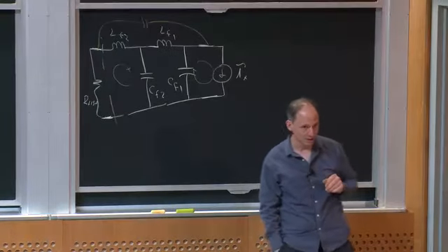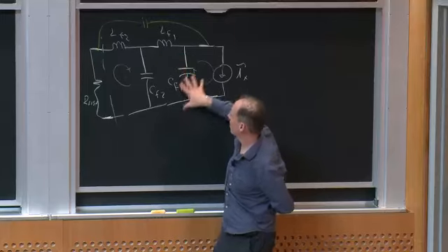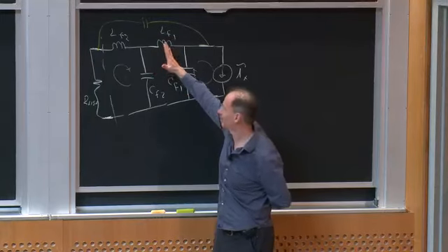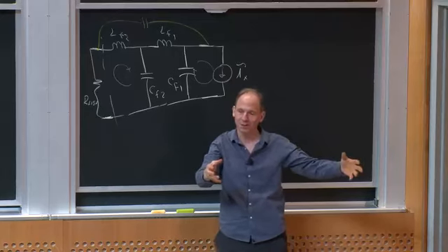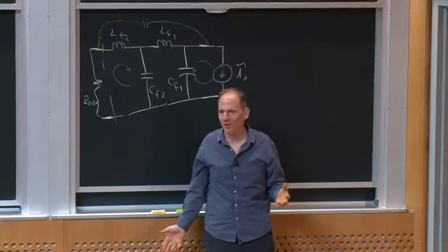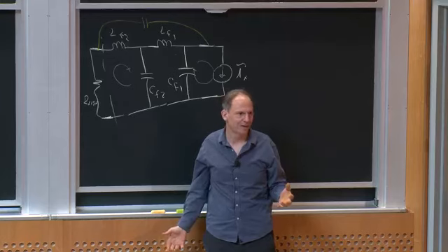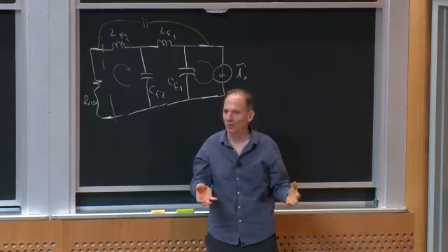What they do in commercial EMI filters is they often will have a filter stage like this and put this inside a shielded box and then have some feed-throughs going to the next filter stage and so forth, and they can build commercial EMI filters that way. And that's great. The sad news about being a power electronics designer is usually they won't let you do that, right? Nobody's going to let you have shielded boxes and so forth in your converter.